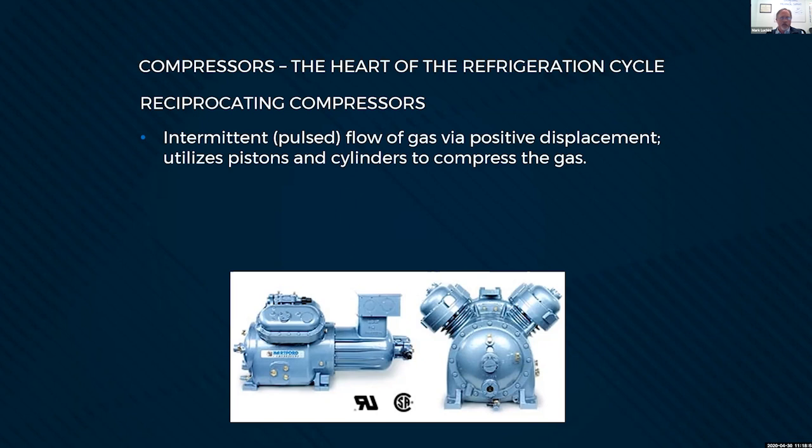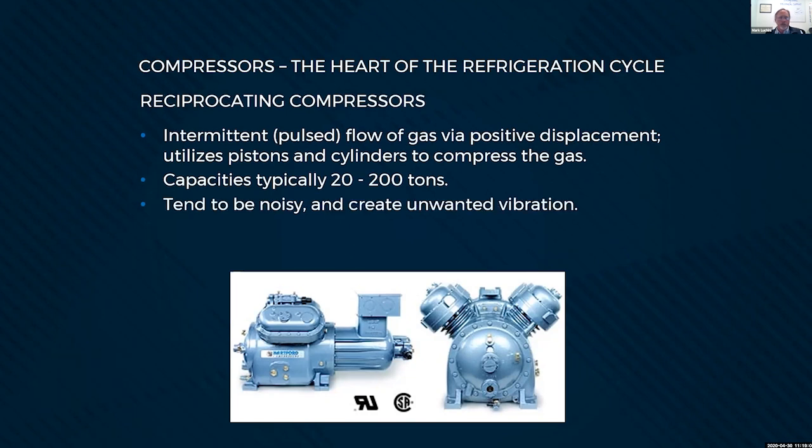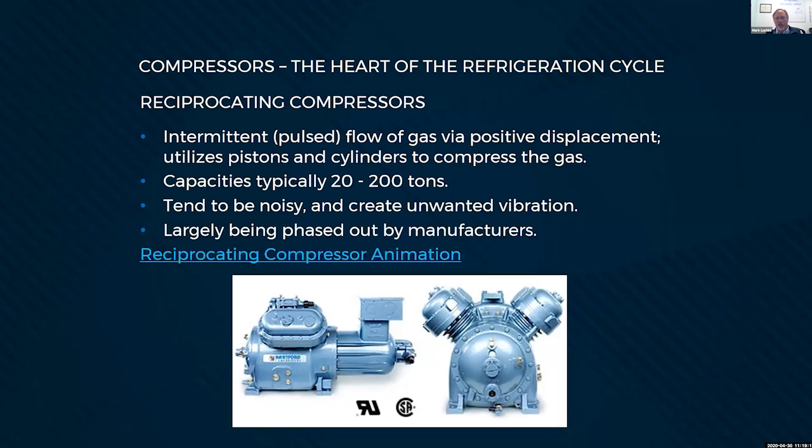It is actually pulsed down through the system. Typically, you're going to see these in capacities up to 200 tons. Unfortunately, they are noisy, and because they are reciprocating, they do create quite a bit of vibration. Most manufacturers have phased these out in favor of other designs.